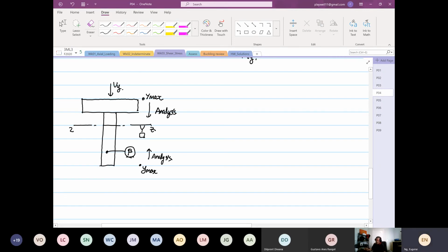And then rule number 4 says what? It cannot cross the centroid. So can someone tell me, what area do we analyze? From the bottom. Yep. To where? To point B. Beta. Well done. This is the area of concern. With that, you comply to rule 1, rule 2, rule 3, and rule 4. It's not based on what? I did not say that the start of the shear force is going to start from Vy. Never have I mentioned that. Never will I mention that.